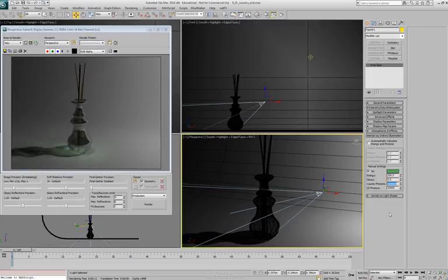Now how do you determine it? Is simply by taking that render. You render it out, you see the quality that you're getting, and then you constantly knock that number down so that you can increase the speed of the render. So you're trying to get it at that in-between balance, having enough photons to get the look that you need within the time frame that you have. So with the caustic photons, let's just go ahead and bump this one up to about 500,000. This will give us a nice range. Let's just re-render this one.